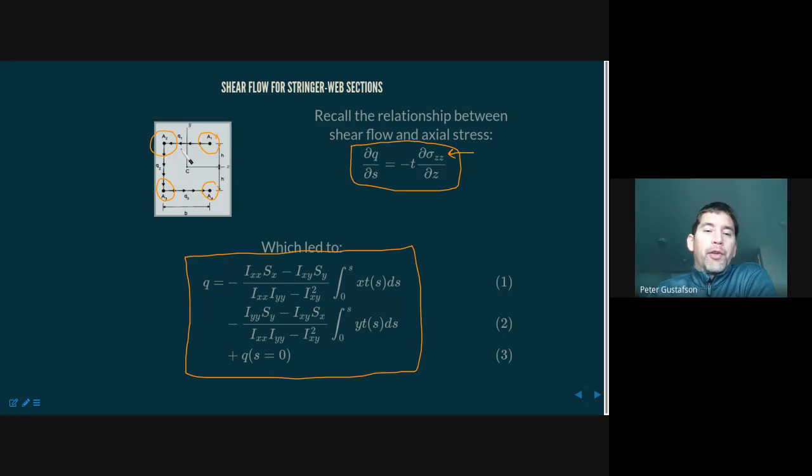And so what we're then going to assume is if it was carrying any compressive load on the bottom side, in the thin-walled portion, that would likely buckle, and that compressive load would functionally go away and be carried by something that was more rigid. And we can make a similar argument at the top. Well, if we're not carrying any compressive load in the thin-walled section on the bottom, then are we really carrying much of a tensile load in the thin-walled section at the top? Actually, you could make an argument that it's possible for that thin-walled membranous type material to carry load.